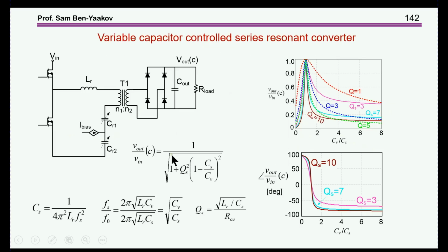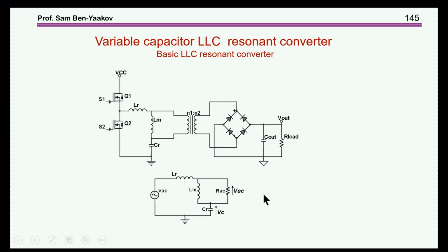So that's a technique that was developed by Professor Steigerwald from General Electric, he used to work there, to replace this non-linear circuit by a resistor. How do you do it? You look at the power dissipated or consumed by this part, and you calculate a resistor that will consume the same power.